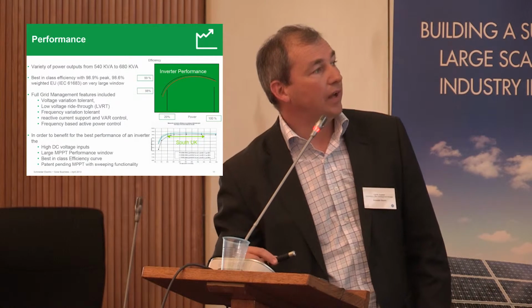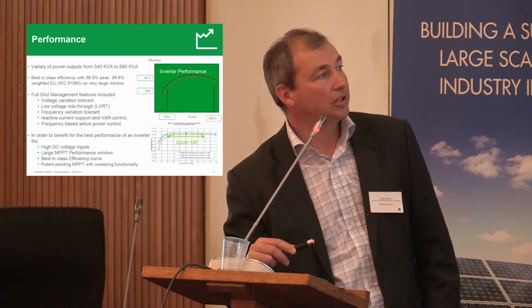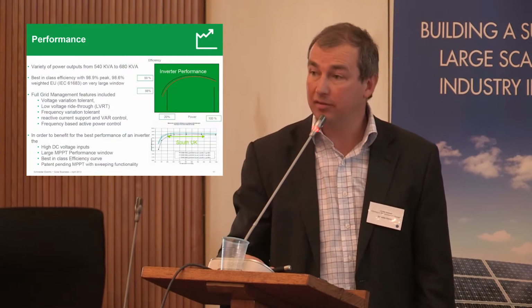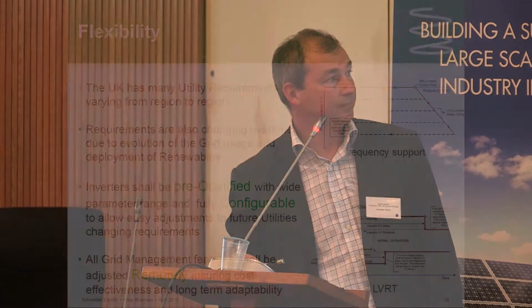We also want an inverter to have the ability to cope with many changing parameters due to the environment. I mean, a cloud goes over your PV plant, you can't control that, okay? You have to be prepared for that. Multiple MPPTs. You have change of DC voltage due to the degradation of the modules, or the current will degrade, the power will degrade, then the evolution of the best performance of your inverter is going to be affected for the 20 or 25 or 30 years of your efficiency.